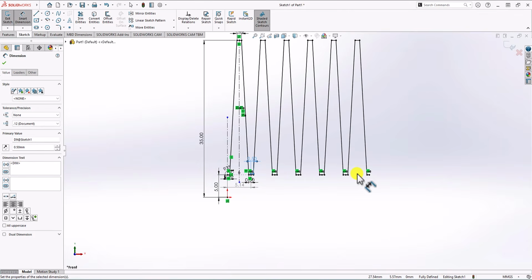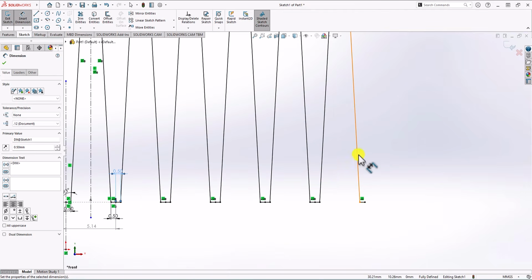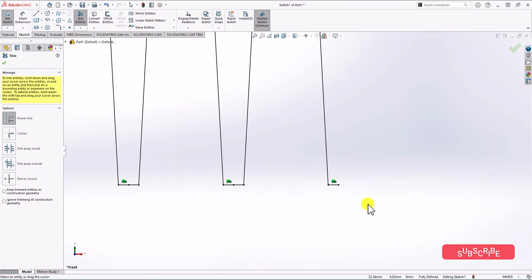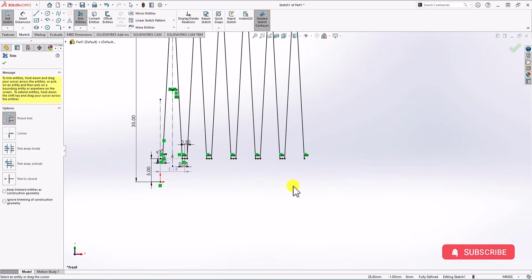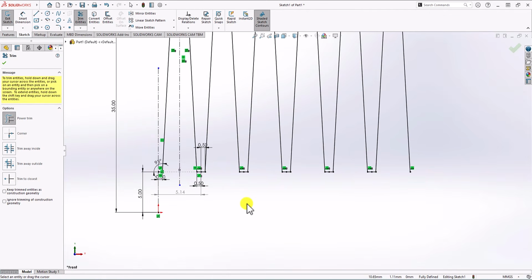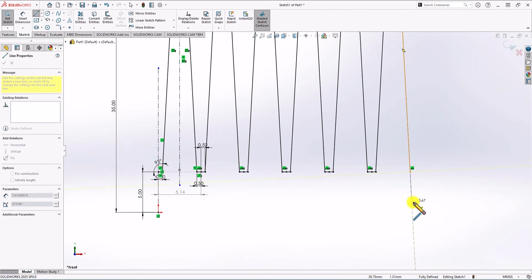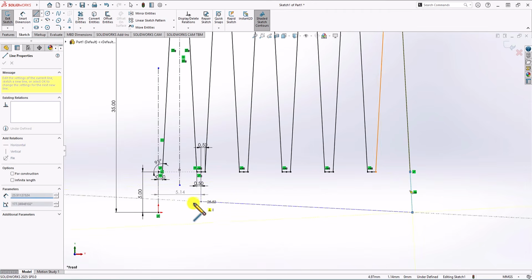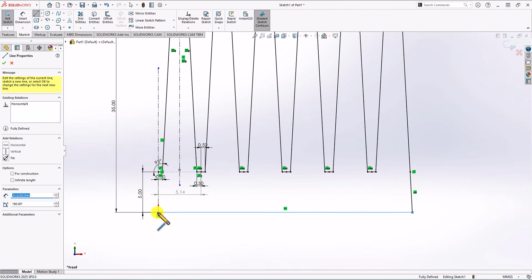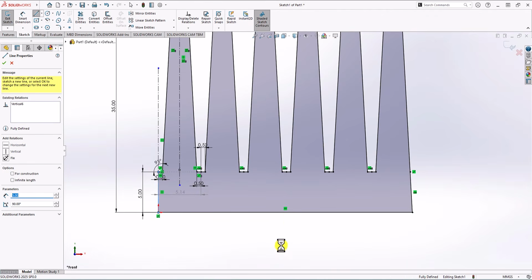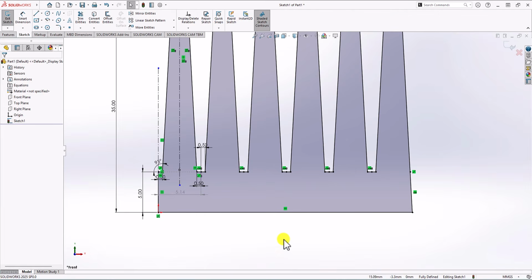Okay, that's great. The only thing that we need to pay attention to is that we don't need this small line at the end. So basically, the line that you see here, we should continue it to the base, and then we need to go to left. So what I can do, I can click on Trim command, and then here I'm going to remove this line. Awesome. Next step, click on Line command, and then here I'm going to connect this line, and then I'm going to left. And then I'm going to connect it to the base point. Awesome. So now this is our geometry.